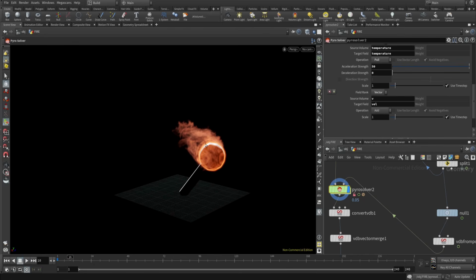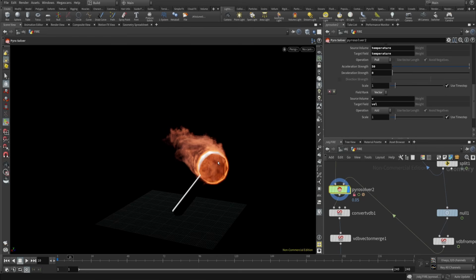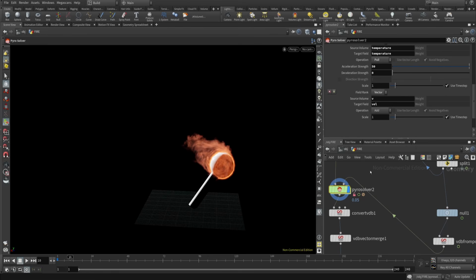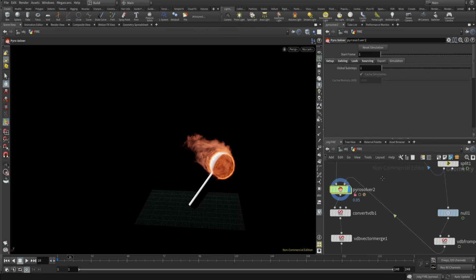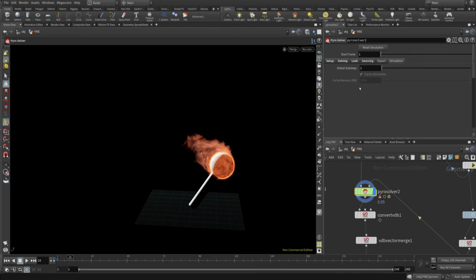we have some stepping issues on this area. One here, another one, another one. Look. To fix this issue, we can use more substeps for entire simulation, but unfortunately when you are working with the minimal OpenCL solver, it's not possible to increase this option. Usually it's giving you some artifact inside your simulation.